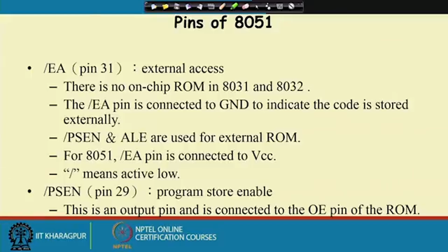For 8051, the EA bar pin is connected to VCC, because 8051 has internal ROM. When the system comes up, the program will start from the internal ROM. So the EA bar pin should be high, so that it does not go to access the external memory immediately.